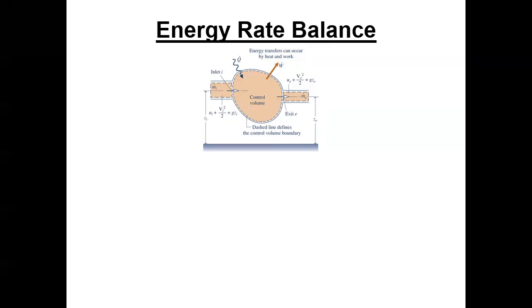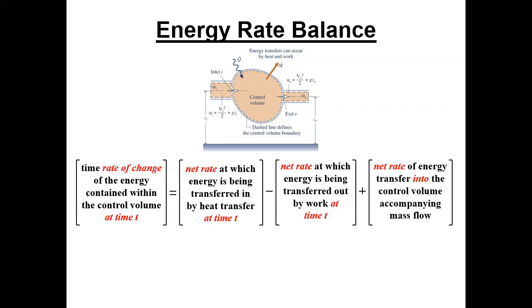And then we've got some mass that's entering. We got an M dot I, and of course it has energy. How do we express that energy that's in the flow coming in? Well, it has internal energy, it has overall kinetic energy, VI squared over 2, and it has potential energy. That's the possibility, and we got the same thing on the exit side. So that's about all that's in the picture. Now let's see what he says.